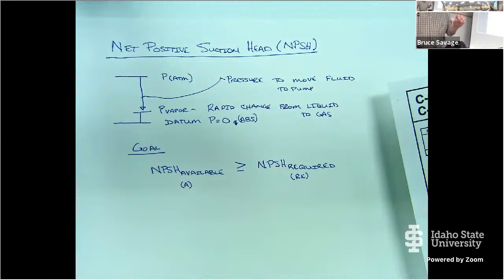Let me give you a little thought concept here. Let's say it was down in California and we had a system. We put a pump on that system, and the pump worked great on that system. And we came up here to Idaho and we had the exact same system, same temperature of the water, same pipe length, same everything, lifting at the same elevation, and we stuck the pump on this system and it didn't work as well. Why? Lower atmospheric pressure. Lower atmospheric pressure, yeah.